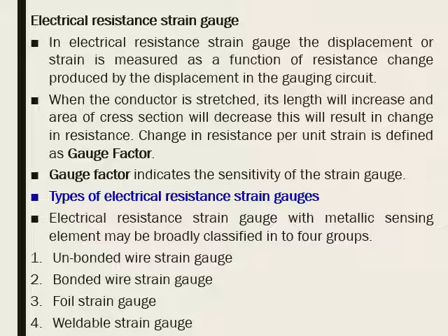Piezoelectric strain gauges are active devices. The strain sensing material is generally barium titanate. Compared to piezoelectric transducers that use quartz as a sensing material, the strain gauge provides an electric charge on its surface which is proportional to strain and can be measured with charge amplifiers. Those are all about the other types.